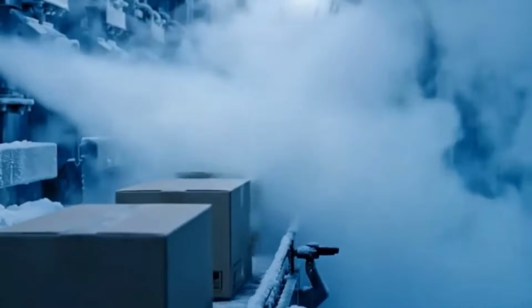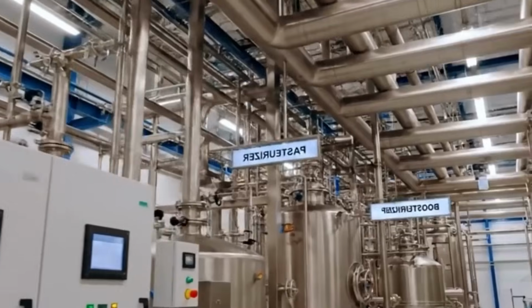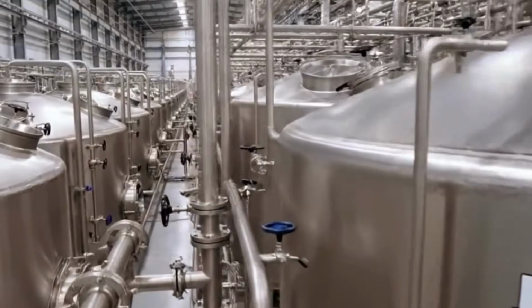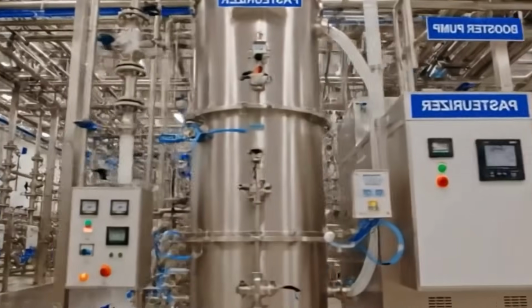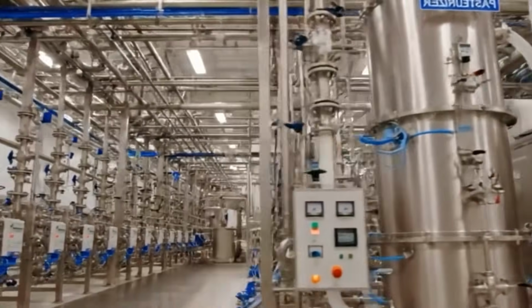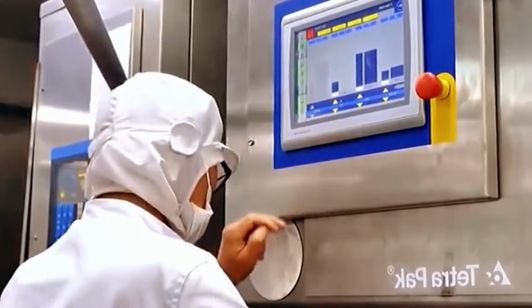Packaged products proceed to check weighers and metal detectors for final inspection. Weighing systems use dynamic load cells to ensure each item is within ±1% of target weight. Metal detectors with triple coil arrays scan for ferrous, non-ferrous, and stainless steel contamination. Rejected products are removed automatically from the line and logged in the manufacturing execution system.